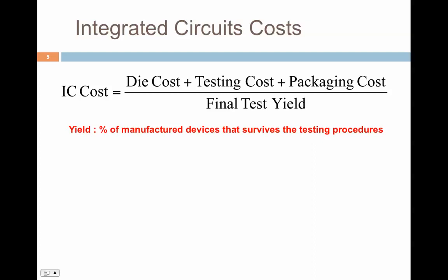Most often, many of the costs are fixed and have nothing much to do with computer architecture. But one thing that we control a lot is the die area and the amount of components that we want to put on the die, right? As architects, we build multipliers and adders, and we want more memory. All of that directly translates into requiring more die area, which translates into increasing the die cost. And that's why we are looking at all of this.